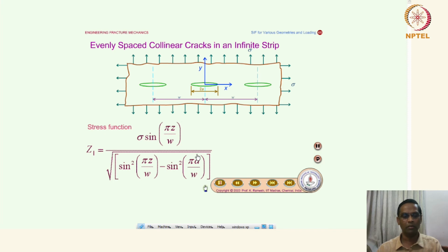introduce a by W, even the energy release rate was normalized, right? By looking at the different crack lengths, after introducing the factor a by W, as a constant beta, the G also converged into a single value point. So similarly, when we bring in the factor a by W, there are so many problems that can be solved.